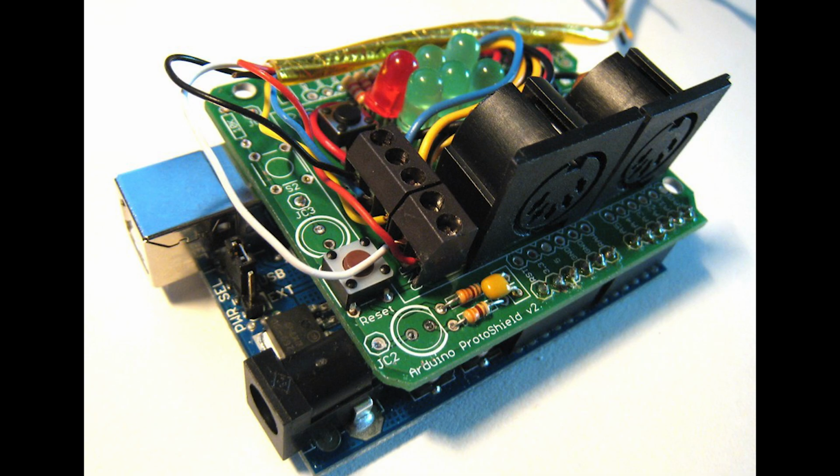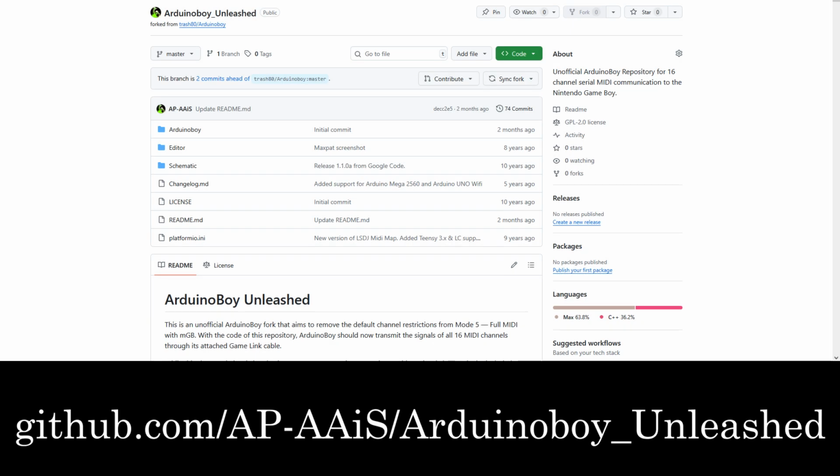However, if you're using an older Arduino Boy interface, you'll have to change out the control software of the Arduino Boy with the software of a new Arduino Boy fork that I've named Arduino Boy Unleashed. This new software is required, since the original Arduino Boy code only sends out the MIDI signals that belong to one of the 4 MIDI channels that the APU generators of MGB have been assigned to with the max editor. Without any changes to this behavior, all other signals are simply ignored.